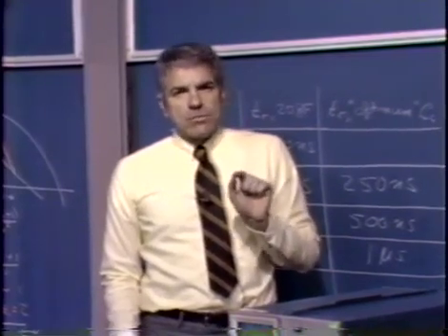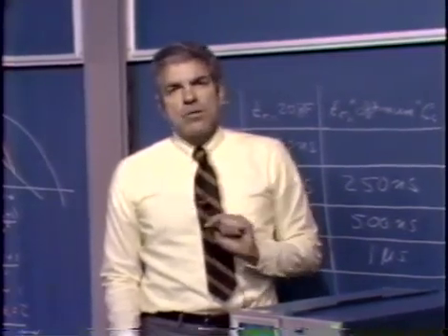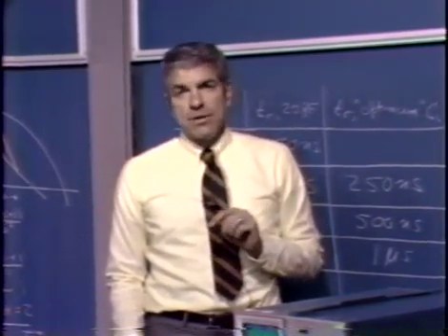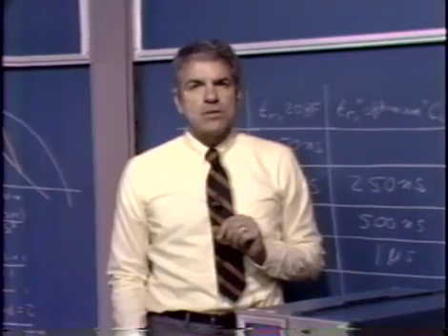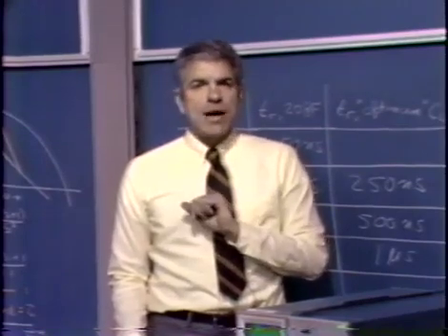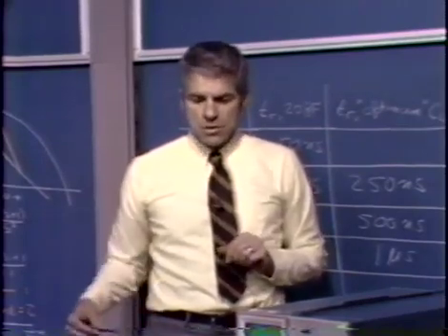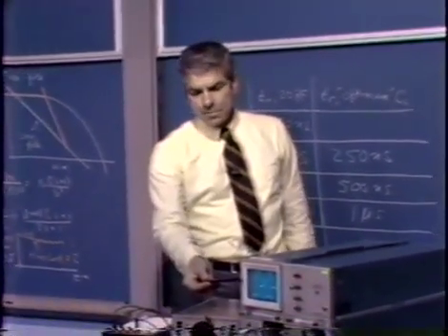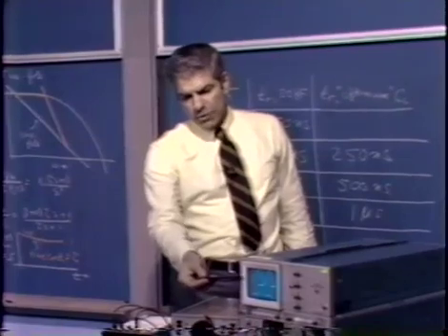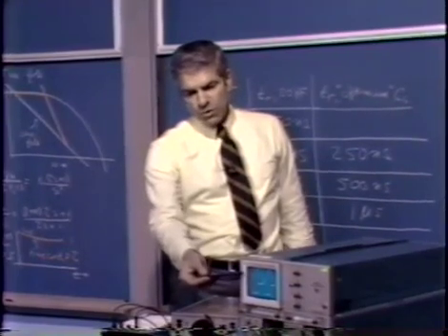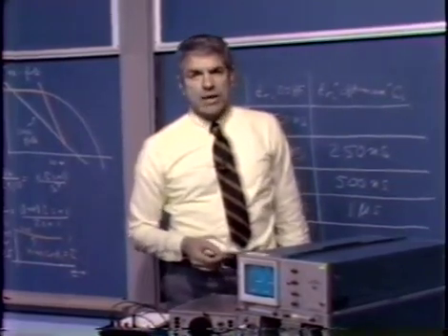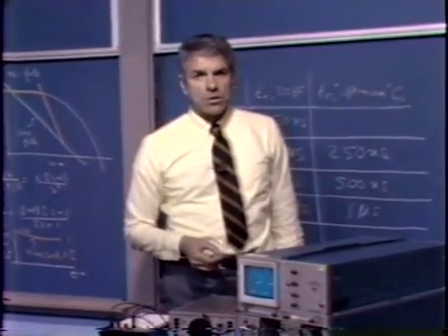Fine, if we have a triangle wave at the output, and that's the integral of the input, of course, the input is the derivative, with some scale factor, of that output signal. We have a triangle wave at the output, we have a square wave at the input. So this is perfectly reasonable. This is the sort of response we'd anticipate if we forced a triangle wave at the output, and have an amplifier whose open loop transfer function rolls off as 1 over S.